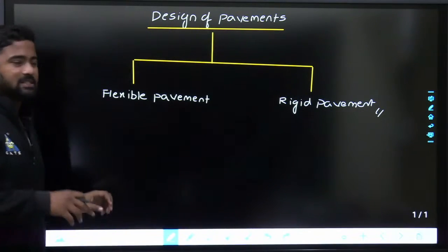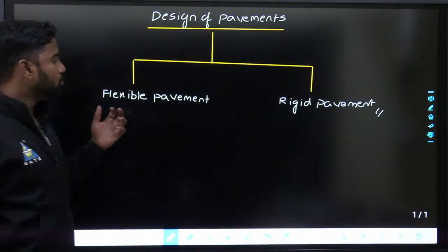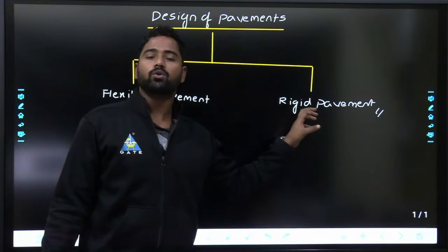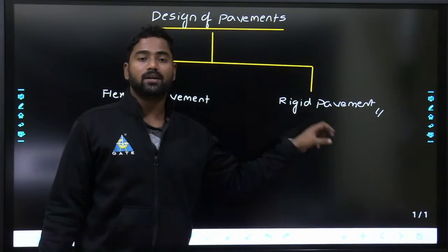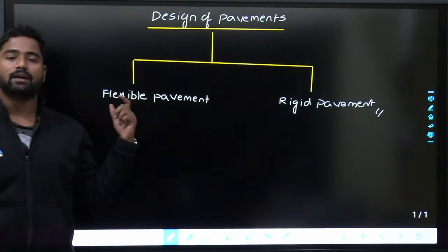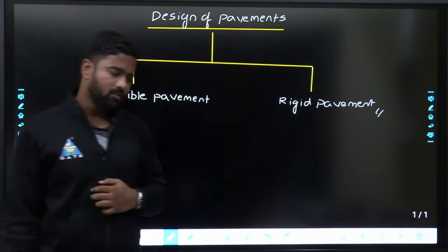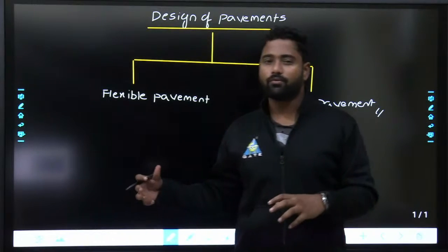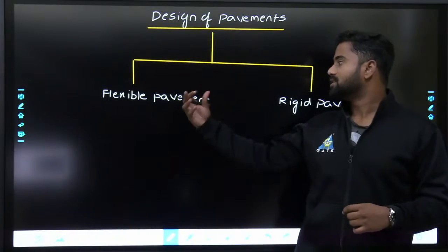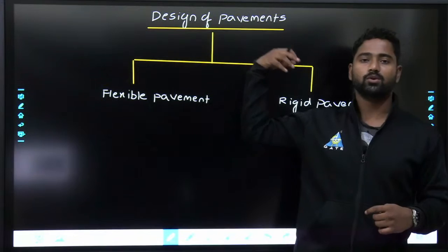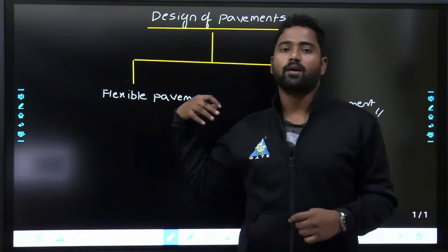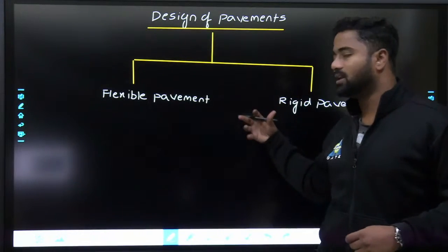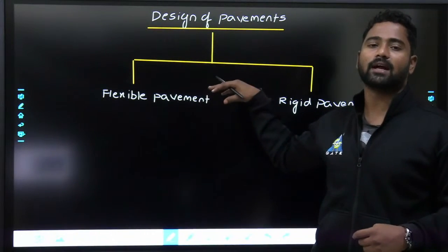And the name itself says flexible pavement means it has more elastic nature. Rigid pavement has very less elastic nature, and for failure here you will see brittle failure, whereas there you will see ductile failure. Normally whenever we are designing highways also, we are going for a composite thing, that is a flexible bituminous course over the cement concrete roads. Fine. So that we will be having both strength, and the failure will also be in the form of ductile failure.